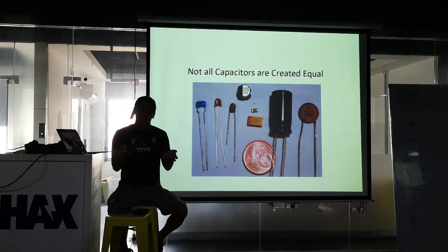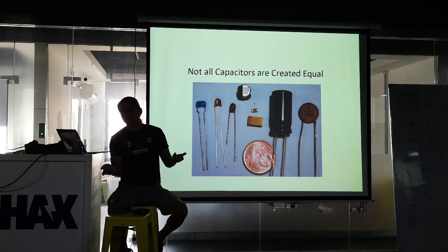So now you're on your workbench and you have this tantalum capacitor on your input filtering out all the noise. You can pass FCC, whatever it is. You plug it in, plug it out. Nothing's wrong. Maybe 100 times on your workbench. But they fail like 1 out of 10,000 times in this way, right? When you push it high. So then you go to production. The first 10,000 units ship, and someone posts on Instagram a picture of their unit, you know, with a scorched capacitor and smoke coming out of it, and now your reputation is ruined, right?